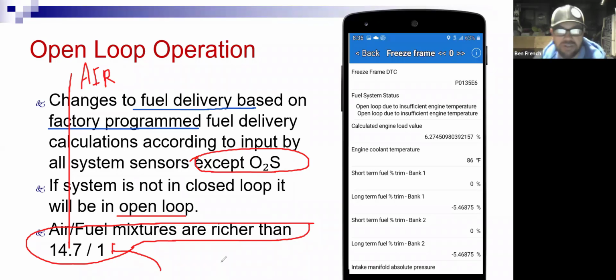And we do it in pounds because it makes the numbers more palatable. If you did it by gallons, and sometimes I get on a wild tangent and we calculate it out, it would be something like 9,000 gallons of air flowing through the engine to burn 1 gallon of gasoline. Pretty crazy numbers. So 14.7 to 1, we have a fancy name for this. We call it stoichiometric.